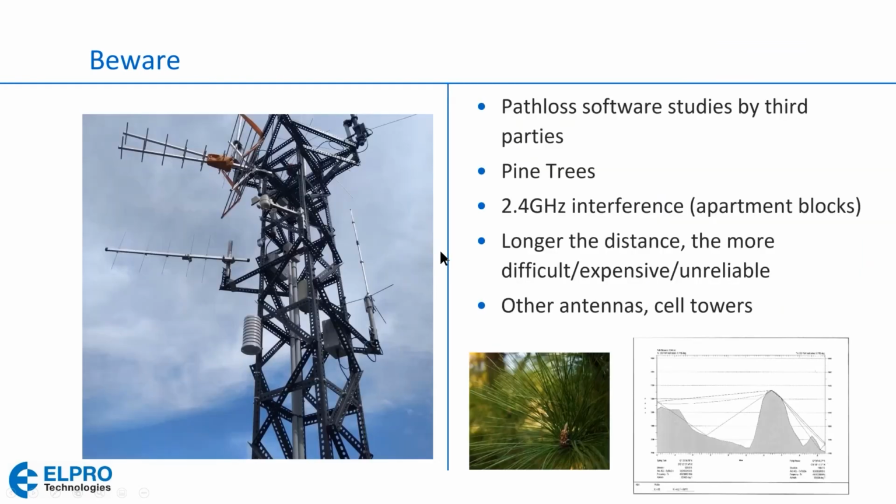Okay, some things to be aware of. One systems integrator I was dealing with had a Pathloss software study done by a third party. This is the program down here. I replicated the exact same program with my Pathloss software and found that the radios would not link up. So I would be careful of getting into a position where you're guaranteeing reception based on a Pathloss study